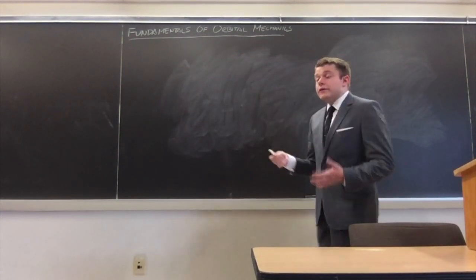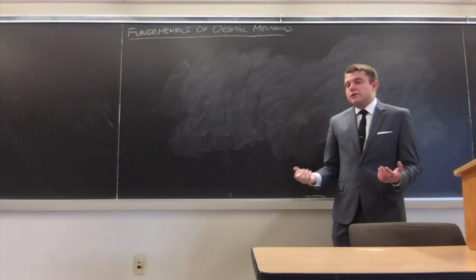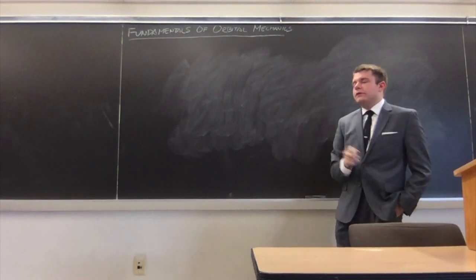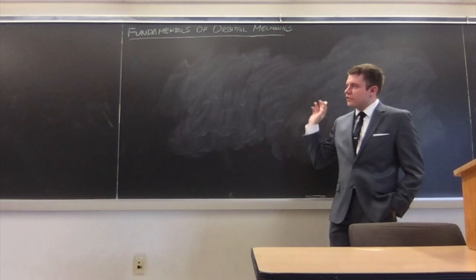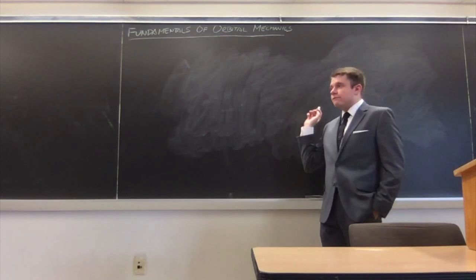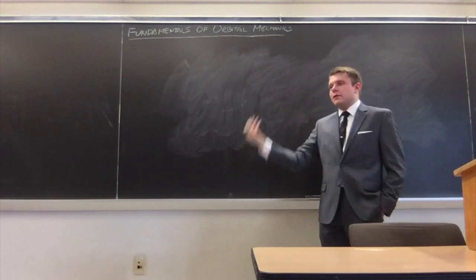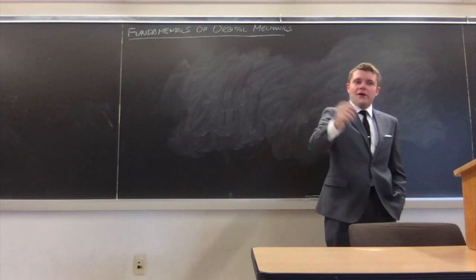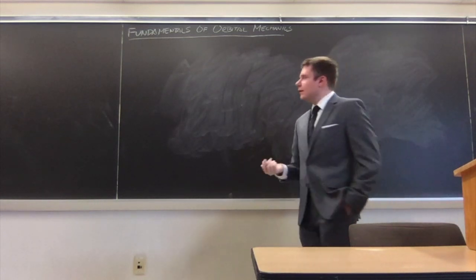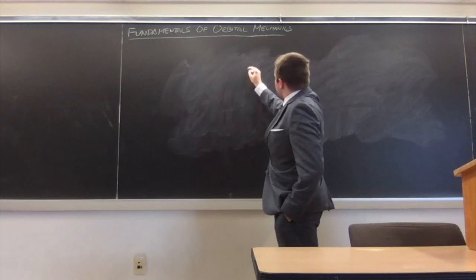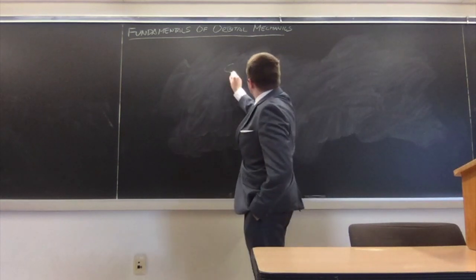And a lot of it relies on the concept of specific impulse and the concept of effective exhaust velocity. And counterintuitively, the lighter the molecules you're exhausting out of the back of your rocket, the faster you can accelerate them, and the higher your specific impulse. But that comes at a cost, which is reduced thrust. So, broadly speaking, there are three different classifications of rocket motors.